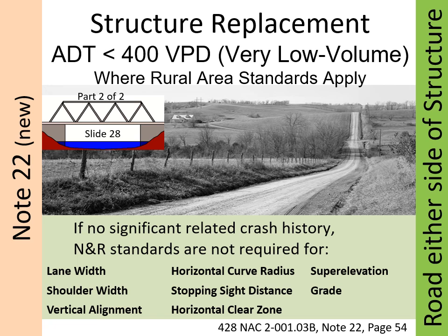Keep in mind State Statute 60-6,190, which requires a minimum 35 mph posted speed limit in rural areas. Also, the roadway must have proper signage. Considering the lifespan of structures, it might make good sense to not have a potential liability out there for the next 60 to 70 years. Remember, these are minimum design standards.